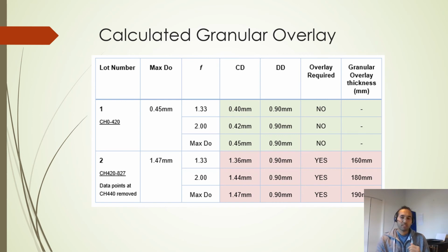For section 0 to chainage 420, so section 1, chainage 0 to chainage 420, you've got very, very low deflections. So you've got cracking, but you've got very low deflections. Resurfacing is recommended. You could seal the cracks so the water doesn't get into the pavement, but at this stage it doesn't seem like any overlay is required. Having said that, let's go to the next slide.